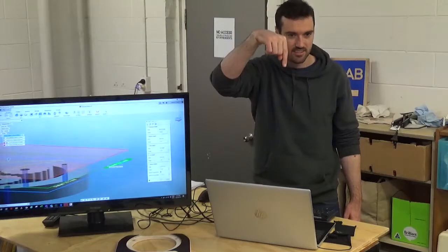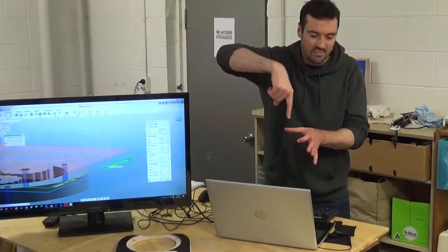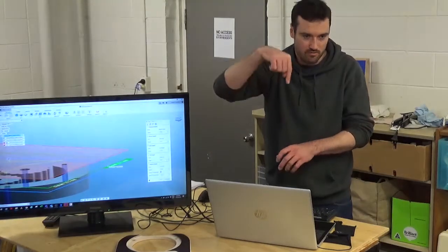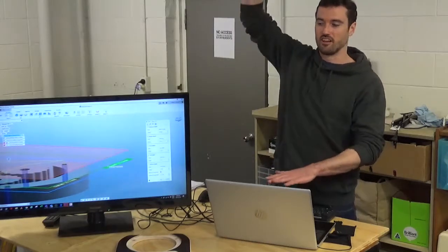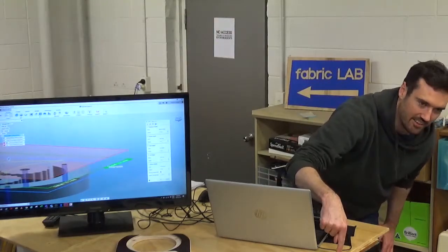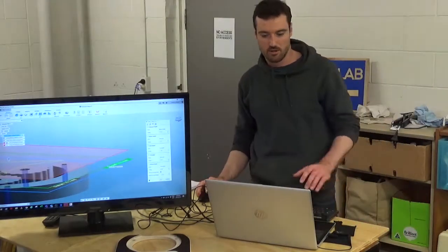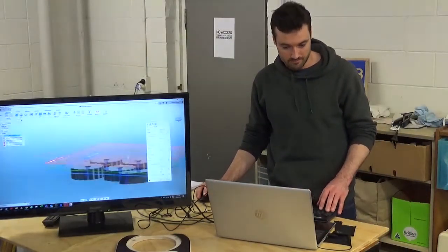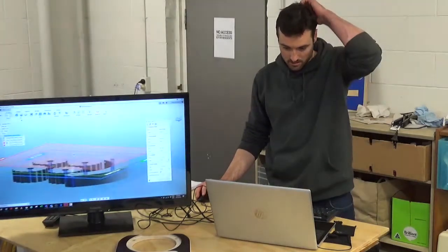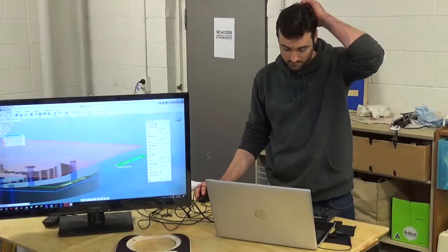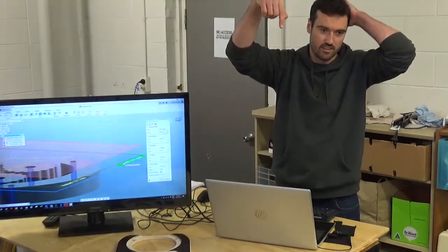That's when it will start to do that. So it's assuming that it's actually going into material from that point, just to be safe. So you don't go really quickly into the material and then start cutting. It starts cutting a little bit higher just to make sure. Then it starts from the feed level or from the retract level? It'll start from the feed, but as it comes out, it'll retract to the retract height. Okay. And then it'll go back.